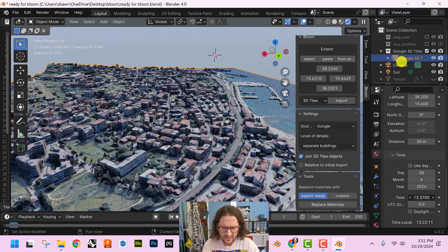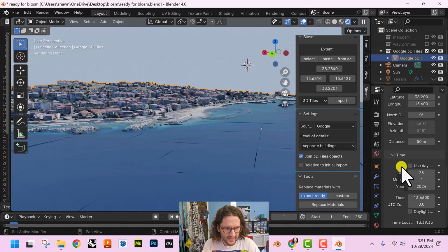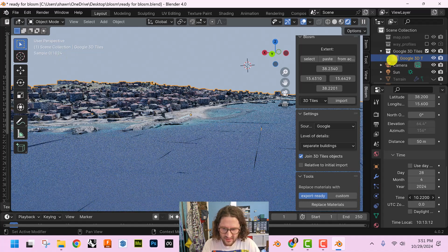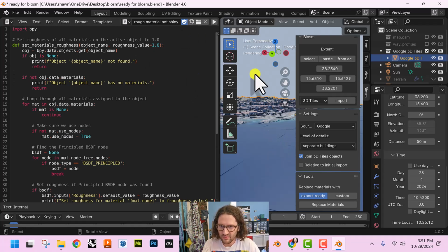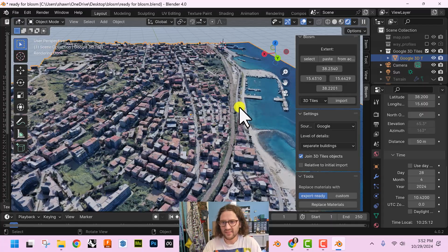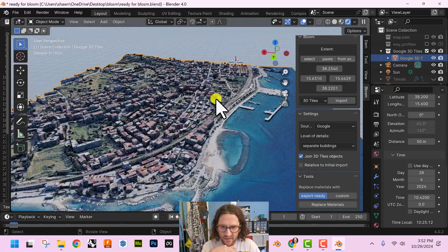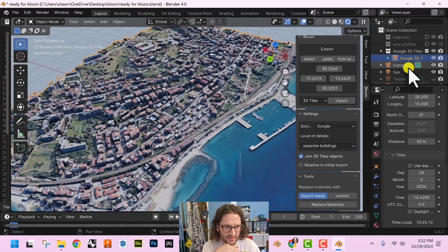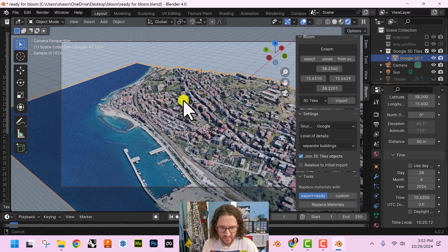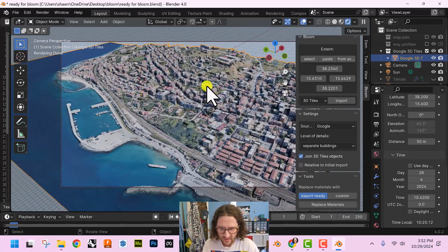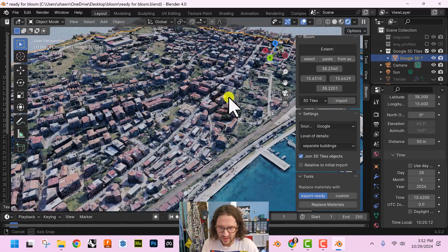But you might also notice the surface is a bit shiny. It's probably shinier than it needs to be. So that's what that script is over on the side. While this is selected, pull this out enough so you can see this plus sign or the play, and then click that just once, then you can close that. That's why I made that there, to make this not shiny. So if you want to do any renderings, 0, if you have a number pad, goes into your camera. Holding shift and pressing down on the mouse wheel can pan it when you are in the camera. I can just leave the camera or whatever.